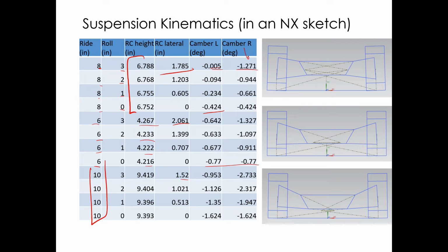It's usually easiest to move these points around. These ones have to fit inside your wheel, which is interesting, but these points here, you have to move those around, and you have a lot of freedom at these points, usually these upper points. But this point and this point really change things a lot when you move them around. So there are other things that are impacted by this too that I don't really have the time to go into in this video.